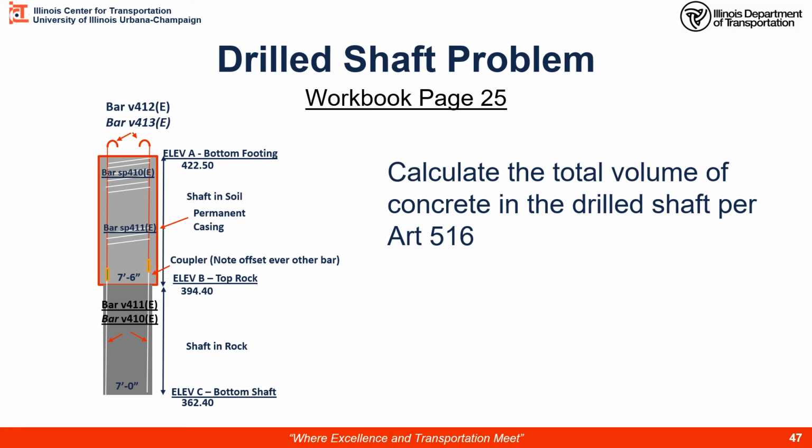There's a lot of detail on the steel, but we're only here to calculate the volume of the concrete in this drilled shaft. Remember, a drilled shaft is a shape of a cylinder, right? So we need to know how to calculate the volume of the cylinder. And we have basically 2 critical pieces of information here. We have some elevations and then what those elevations represent, whether it's in soil or in rock.